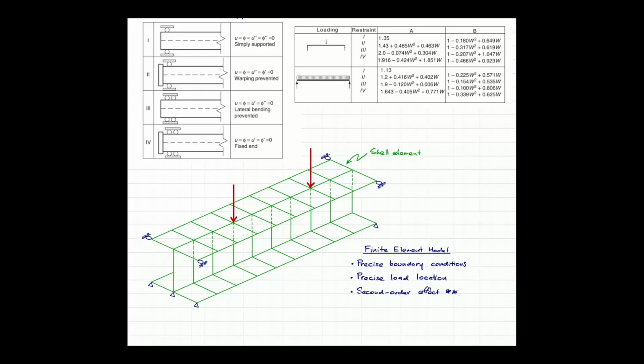You have no idea whether the coarse aggregate used in the previous batch and this batch have pretty much the same aggregate size or not. Sometimes you get it from the bottom of the stockpile, whereas another batch is taken from the surface of the stockpile, the size could be different.